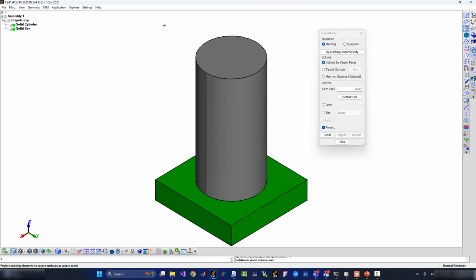Then, when you are meshing a prismatic solid like this one, it works always best. Sometimes you are unable to mesh unless you give what we call a target surface. That is, the program oftentimes wants you to pick a planar surface so that we help the grid generator start with the two-dimensional discretization of that surface, then move in the third dimension of the cylinder.